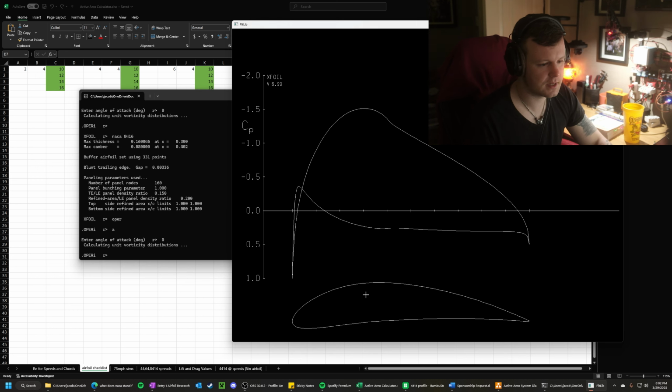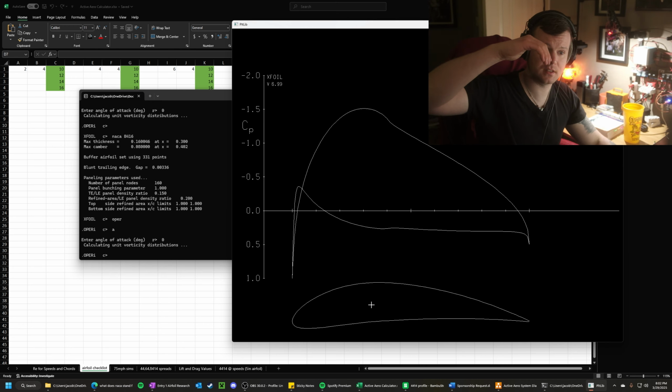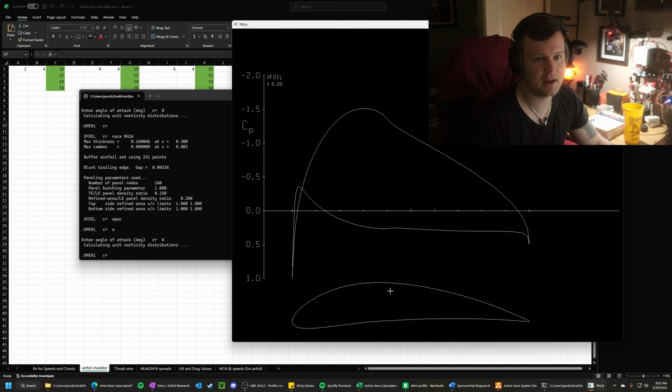And here you can see that we have a much curvier, much thicker airfoil, very voluptuous. And so that is an 8416. It's 1.6 centimeters thick. It's got a maximum camber of 8 millimeters off of the center line, so that means it's a lot more camber. And camber for airfoils just means how curvy it is. So this is a lot more curvy. So this is an 8416 NACA airfoil.